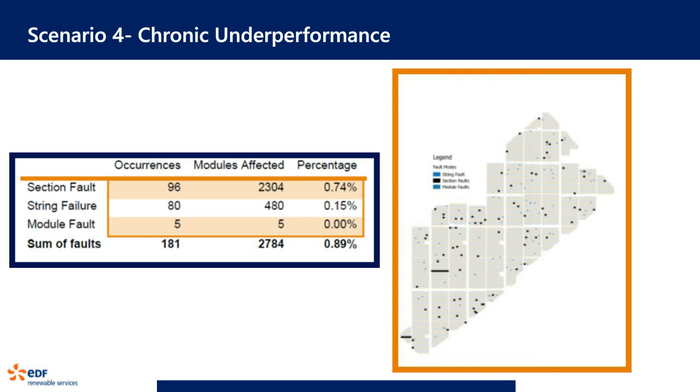When we actually got the agreement to do the first aerial survey, we also negotiated a price for a second flyover, right? Understanding that we would need to validate the results so that we could get the most value out of this information. Because this overlaid with as-built drawings of the plant, we could give very specific locations, right? Okay, technicians, field team, we need you to go out to section 3A, row 34, module places 72 through 86, or what have you, and go out and specifically address these problems and correct them.